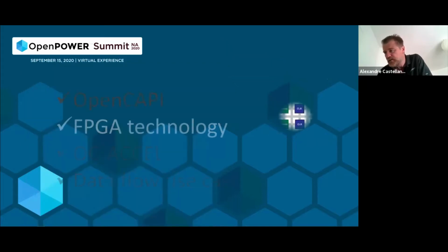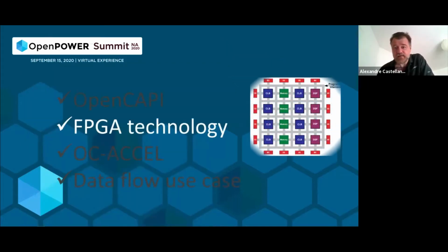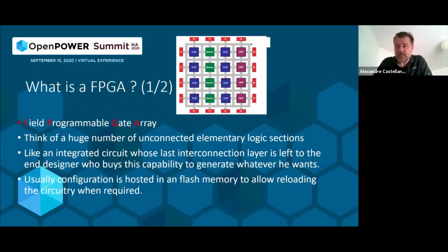So let's begin with the FPGA technology. We'll go into detail on what it brings. First, it stands for Field Programmable Gate Array. So think about a huge number of logic cells that have not been interconnected. The last layer of the chip design has not been made, and it is left to you as a designer to interconnect these. To achieve that, you will be helped by software, which is dependent on the provider. The main provider we work with is Xilinx, so we use the Xilinx suite to prepare this last layer in order to configure the chip to do whatever we need.